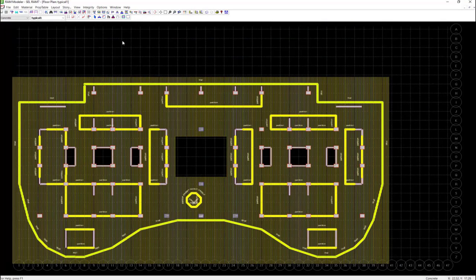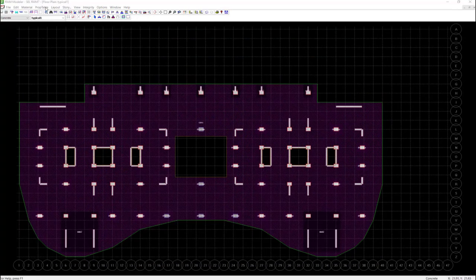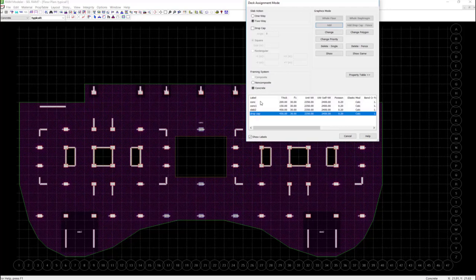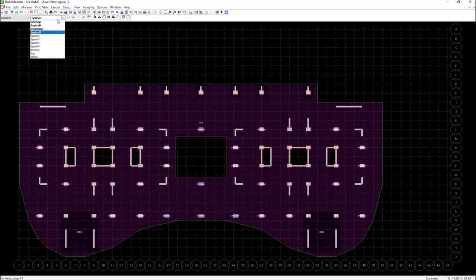Now, this being the podium level floor, I have used only the flat slab, and hence I have added the drop caps and thickened some other portion of the slab. Now the interesting part here is after providing the drop cap, the slab thickening is not done along both the opposite surfaces of the slab, but the thickening is generated along the downward direction for capturing the true effect of the element as it is supposed to be in the practical scenario.